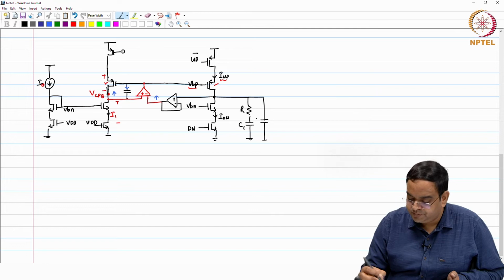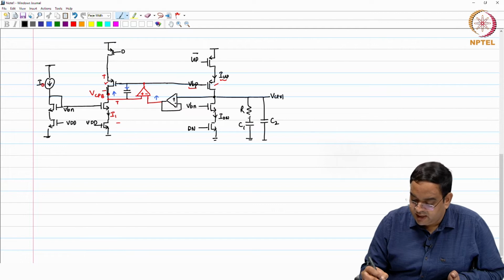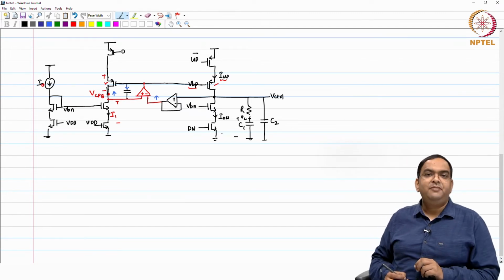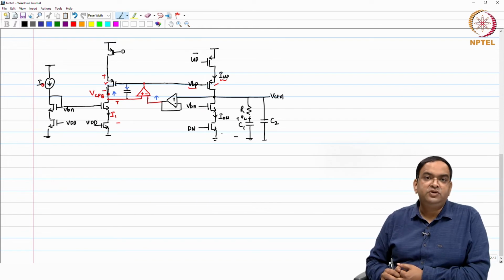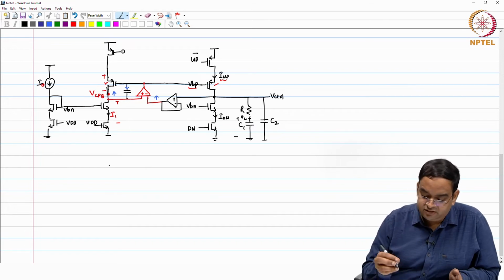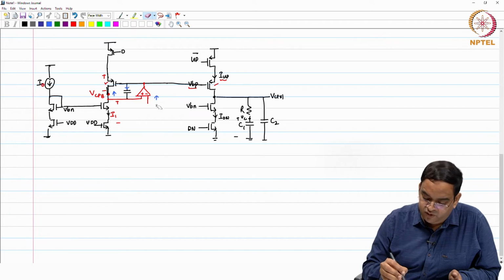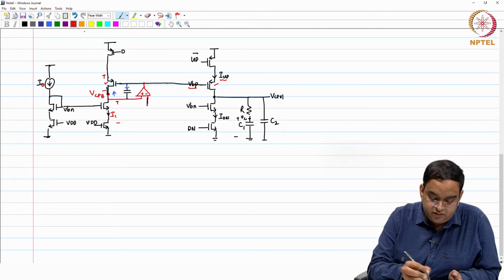Your V control voltage and your VC voltage across the C1 capacitor, the DC value of these two voltages is the same, and it will change only when you require the oscillator's frequency to vary. So, in place of having the reference coming from V control, we can remove this and take the reference from here.